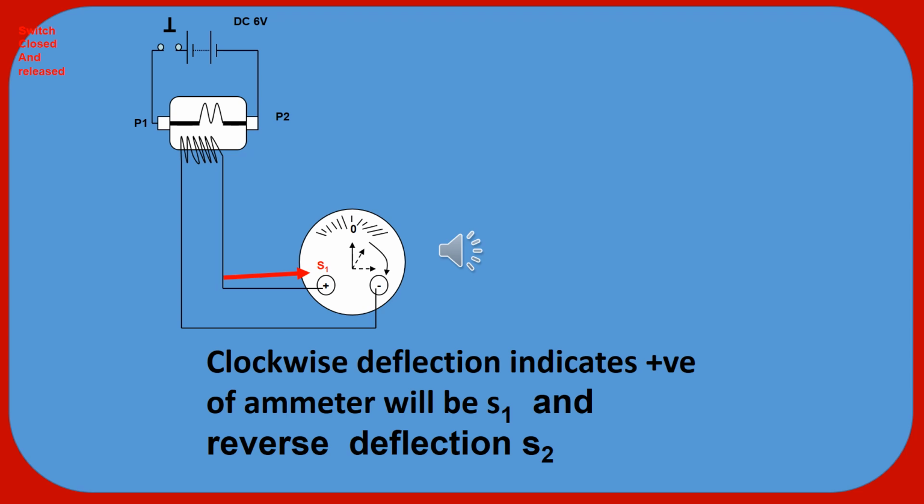That means they have given some guideline on what to connect to S1 and what to connect to S2. They have written CT, PT, so you have to connect at that particular terminal. But to understand this, the electromechanical relay connection is important and better to understand.